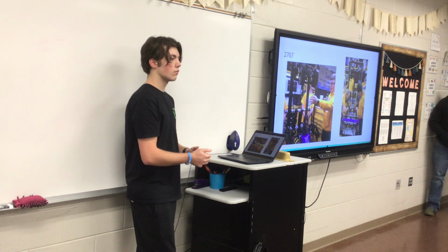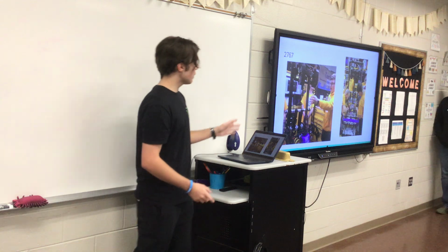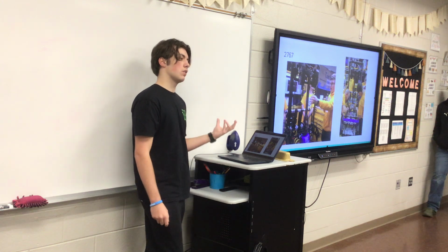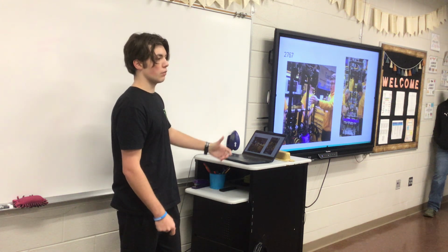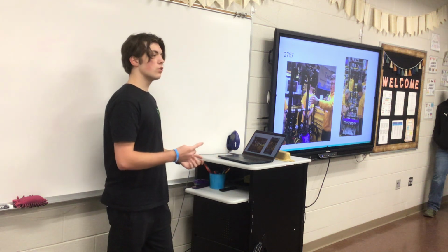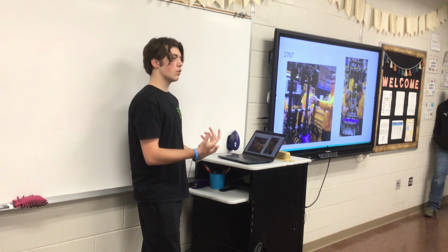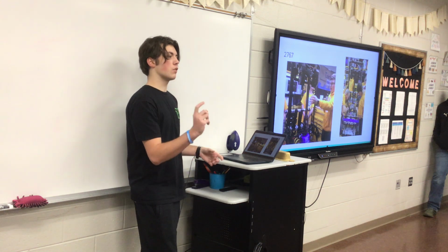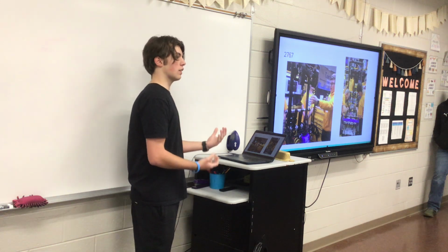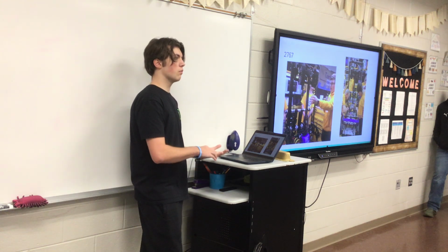Are there any concerns with machining carbon fiber? You need to be a little careful. Like you said, once the fibers get out, they can be very abrasive, similar to working with plain fiberglass or asbestos. But for machining it, you also need to be careful because it can be brittle. So if you're drilling through it, you might want to use a drill bit made for glass specifically, instead of a regular drill bit. You need to be careful about things like that, because it's also going to have a bit of flex. It's not going to be perfectly rigid.